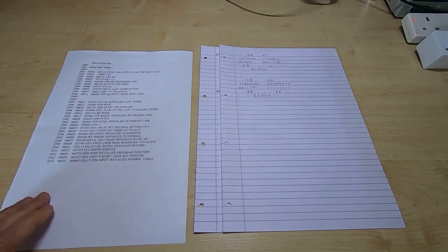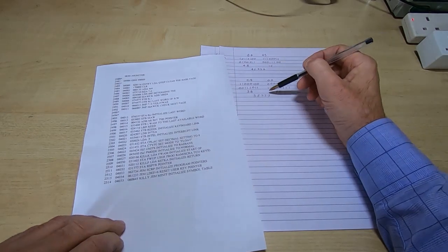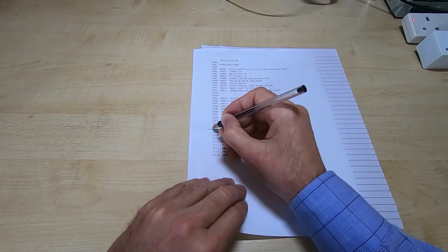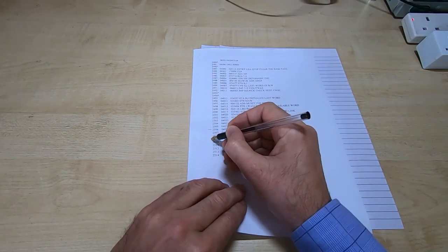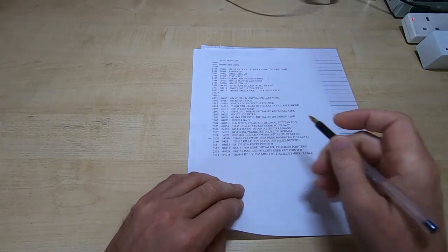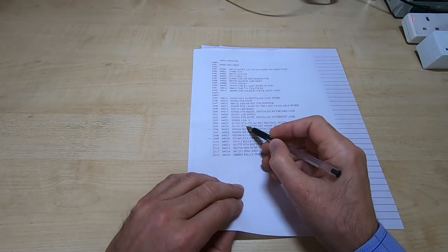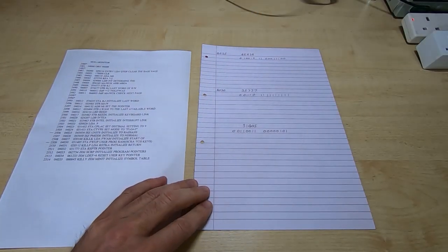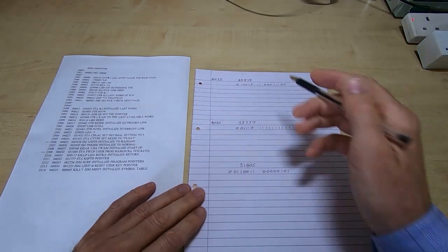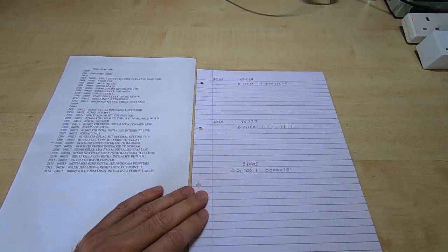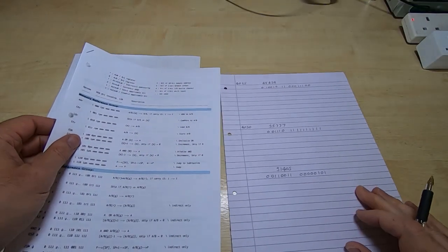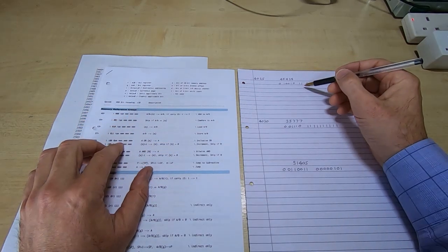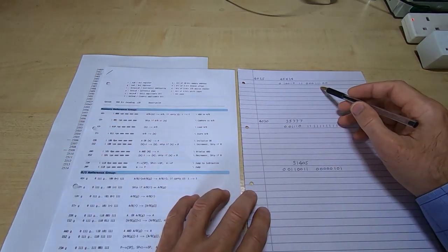Okay, so if we look at the data that we've captured, we captured two addresses. One was at 4025, which is this address, and the other one was at 4030, that's this address. These are octal values. So if we now look at the two instructions, if we interpret what we've captured and see what instructions they should represent and see if it makes sense. Now, this is the one that we captured that was correct, and if we get the instruction set and interpret this particular code, I've turned it into binary here, it just makes it easier to interpret the instruction.